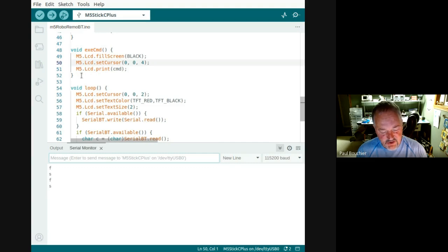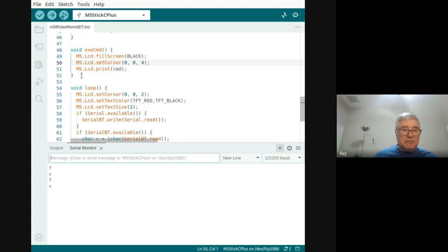You can put an image, which you can set as a background, so you have a picture of your robot. A touchpad, I'm not sure what that is. Keyboard connector, not sure what that is. It's got a heartbeat sender, which will send periodic pulses from the cell phone to the Arduino. The idea is you can use that for a dead man timer. So if your cell phone app crashes or you get disconnected, then your robot knows it's no longer in contact and it should stop. Get too far away from it or something. Yeah, right.